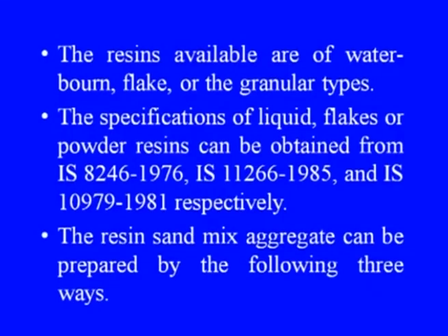The sand composition to be used in making various castings of different materials can be seen from the relevant standards. The resins available are of water-borne, flake or the granular types. The specifications of liquid, flakes or powder resins can be obtained from Indian Standard